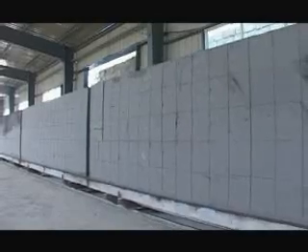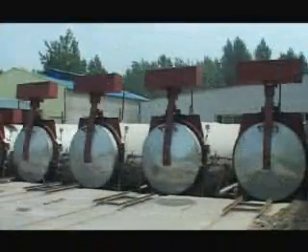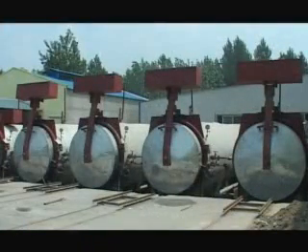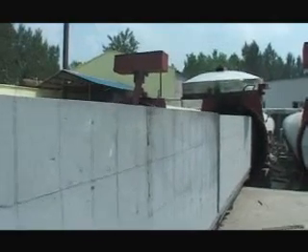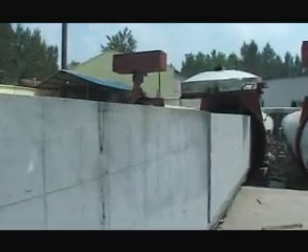5. Autoclaving. The grouped cake is wheeled into the autoclave by the slow-action hoist for autoclaving. After 7 to 10 hours, the cake is wheeled out of the autoclave by the slow-action hoist, and lifted into the truck by the finished product hoist for selling directly or storage. The steam car and the side plate return through the back rails for another cycle.